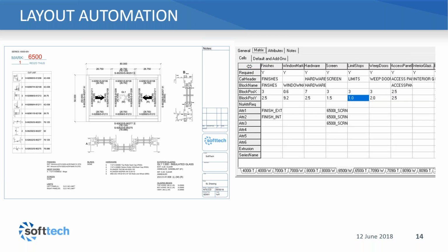A lot of my experience working with CAD drawings is that your CAD drawing is part of your business. It's almost part of your branding. You generally develop your own text styles, your own dimension styles, and sometimes you're sending those drawings off to customers, so they need to look good and represent your business. So this gives you that capability. What we actually did here was we created a template drawing. We loaded in the text styles we wanted, we created the dimension styles that we wanted, and so on, and we used that as our starting point. So you have complete flexibility with how you lay it out and how it looks, and I think that is one of the very important aspects of this.